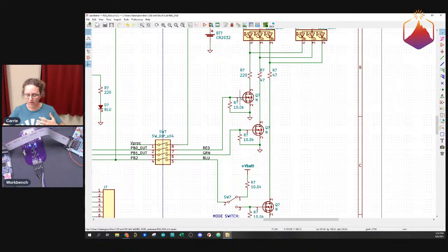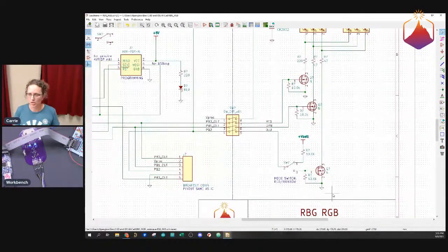They pick up electrical energy from the surrounding environment, so some of the board might be a little charged and some of it a little not charged. Things can be weird when they're not connected to anything. Since gates are pretty sensitive, it's helpful to make sure they stay off when they are not connected to anything. So that's why we pull them to ground with this resistor here. We just make them be at a known potential.